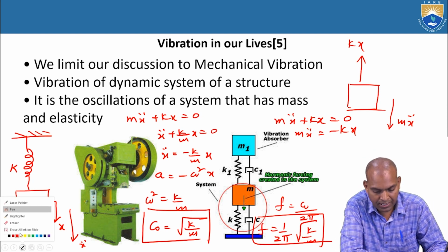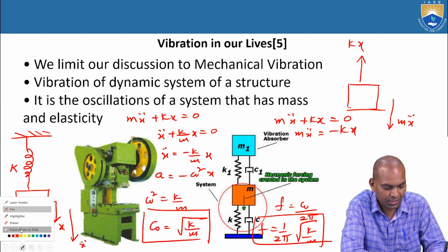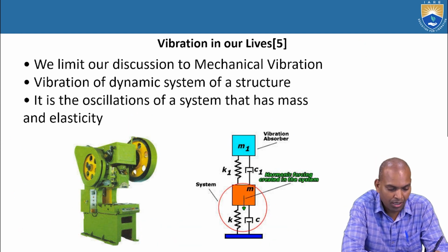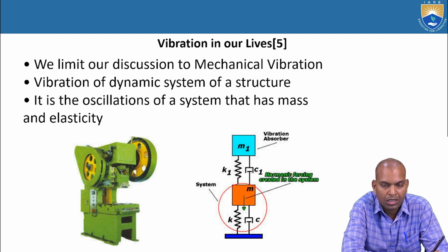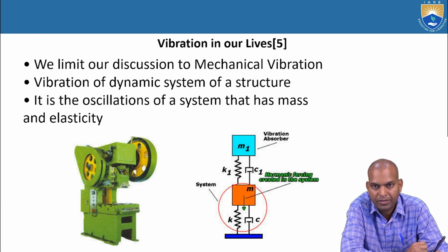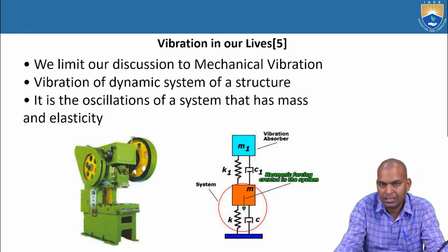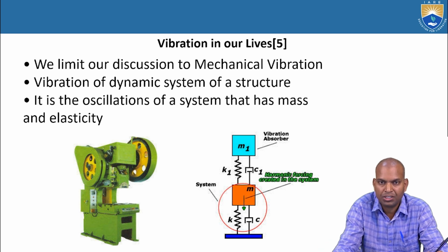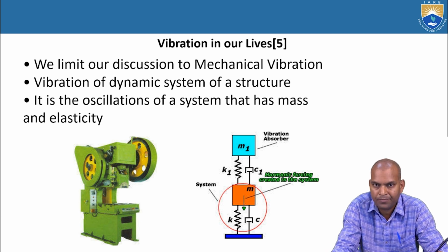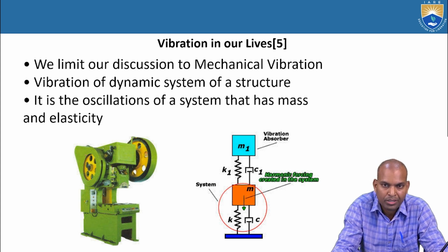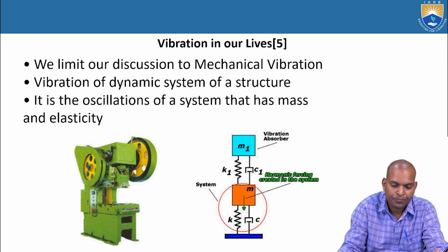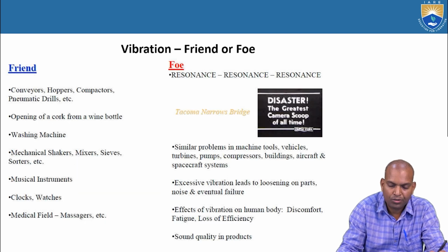Now, these are the explanations of the equations of motion. Further, we'll explain in detail what the displacement equation is, what the equation x equals. Now, oscillating systems, especially when machines are under rotating or operating working conditions, generate vibrations. When those vibrations are equal to the natural vibrations of the system, the amplitude of the vibration increases. That phenomenon is known as the resonance phenomenon. We'll see more and more of it further on.